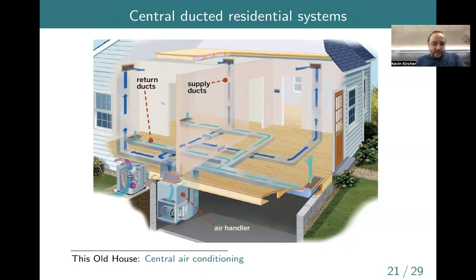So how this works basically is you have outdoor air that's relatively cool, it might be 80 degrees Fahrenheit, something like that. It goes into a heat exchanger where there's pretty hot refrigerant, and then comes out at maybe 90 or 100 degrees Fahrenheit. And that is both going to cool down and also condense the refrigerant out here. Then it goes through pipes inside and through the expansion valve, and gets very cold. In this heat exchanger you'd have super cold refrigerant, and this fan or blower is moving air over that to cool down and dehumidify the indoor air. That goes up into supply ducts.